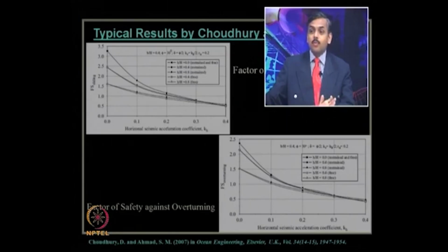When the tsunami wave is attacking, you are concerned about the height of the tsunami. When it is going back, there is no height available. So that is why it is not with respect to the tsunami wave height, but with respect to the height of the water standing on the downstream side, or the soil side. Based on that, you should do the design. Clear?